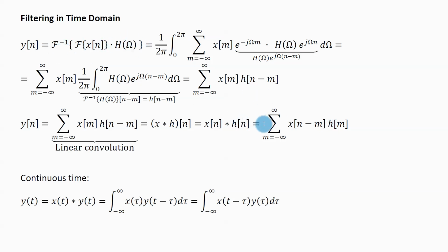So basically all that this does is that it changes the spectrum of our signal. It can amplify some frequencies, it can suppress some frequencies, or it can introduce some phase shifts. And that is the thing to remember. The linear convolution is nothing but filtering, and filtering just alters the spectrum of my signal.